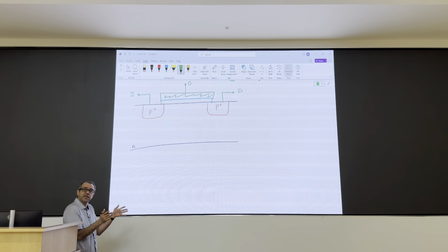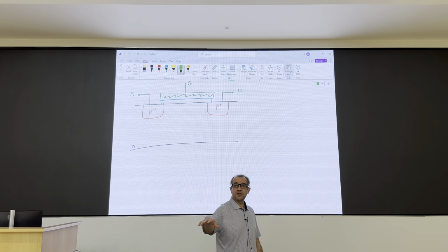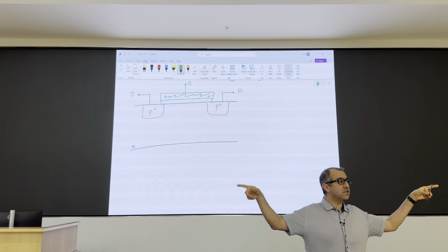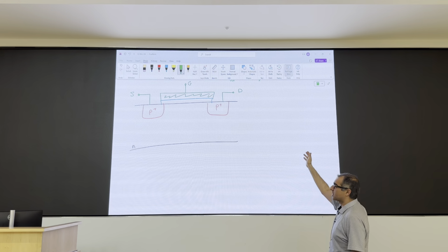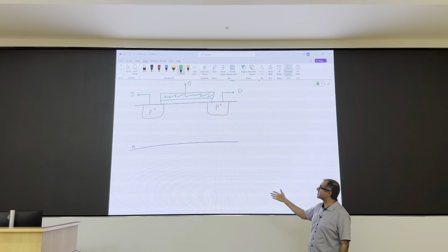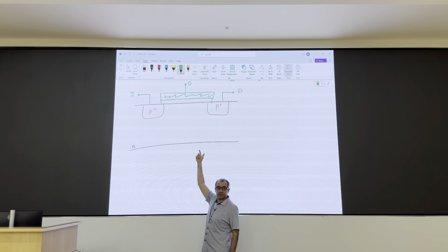Structurally, exactly the same. You just make it on a substrate with the opposite polarity, and drain and source, instead of doping them with N-type dopants, you dope them with P-type dopants, right? And then you can see that all those stories we said before apply here. The only difference is that I want to invert the doping at the surface from N-type to P-type.